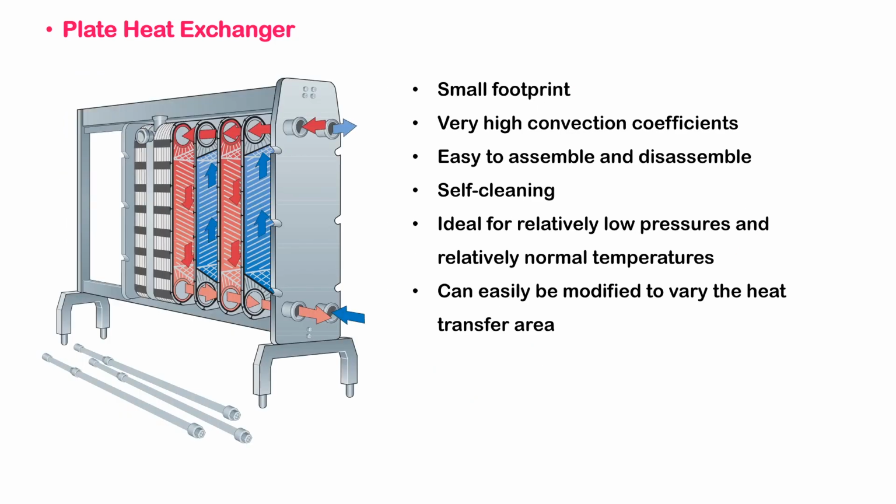Here I'd like to show you more about the flow behavior. You have channels. You have one stream for cold fluid that goes in, and it follows, let's say, the odd-numbered plates: goes into 1, goes into 3, 5, and so on. Then you guide the hot fluid, and that goes into the even-numbered plates, 2, 4, and so on.